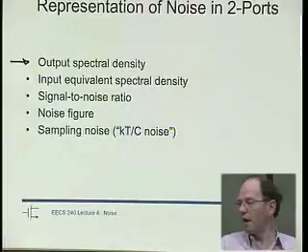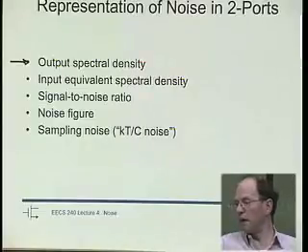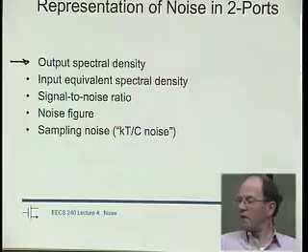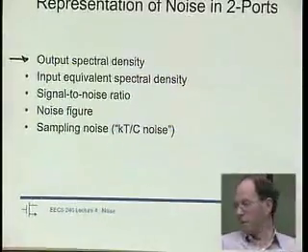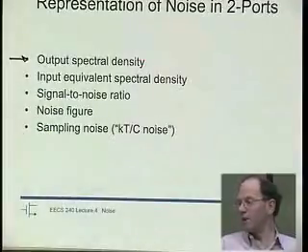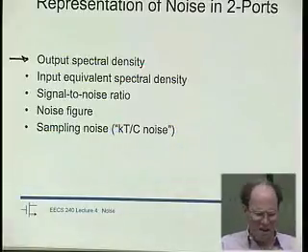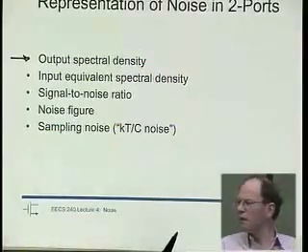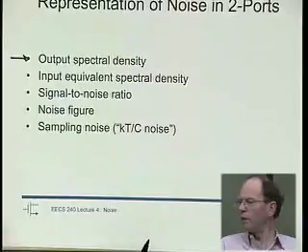If you have a high gain amplifier, well, probably some of the amplifier's noise is also gained up, and we get more noise out of that amplifier. Is that now a worse amplifier than another amplifier that has lower gain and consequently also lower noise? Well, not necessarily, right? I mean, the signal is actually amplified also when the noise is amplified, and so it depends on the gain and so on. So sometimes it's very inconvenient, especially if you had an operational amplifier.